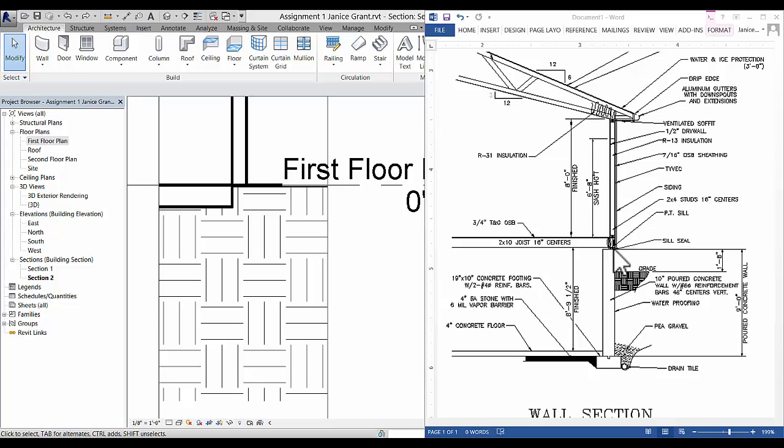And this would be different for commercial, but it sits on this mud sill, which is the 2x6. That's the transition between the joist and the foundation. So in understanding all of that, in order for us to draw the wall section, we'll need to bring this floor over to line up with this wall, and then we'll bring in the 2x component after we've established the extent of this floor and the walls.